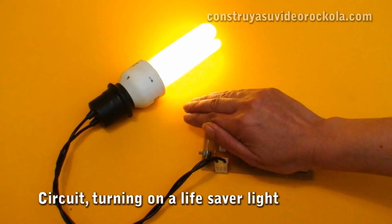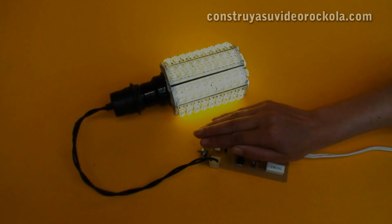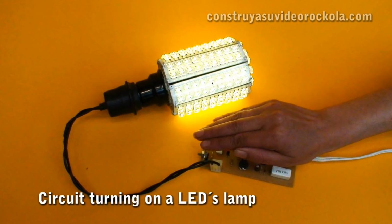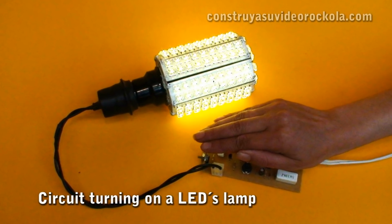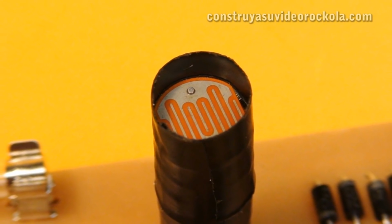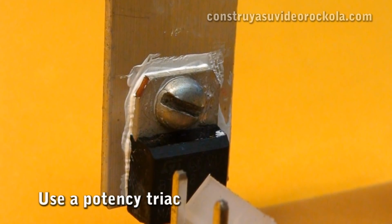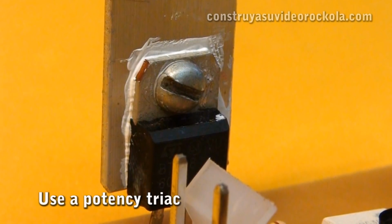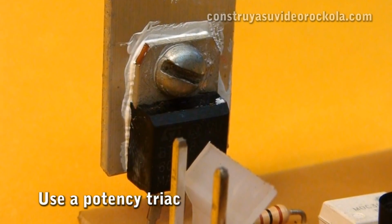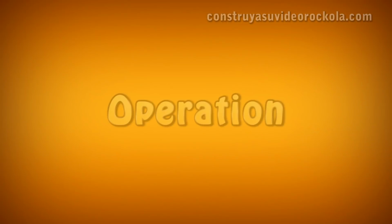This circuit operates with voltage from 115 to 220 volts, no need to make any changes. You can light a bulb up to 100 watts. If you want more powerful lighting devices, you should only change the BT136 triac for one that supports more amps, such as the BTA08-600, which supports up to 8 amps.